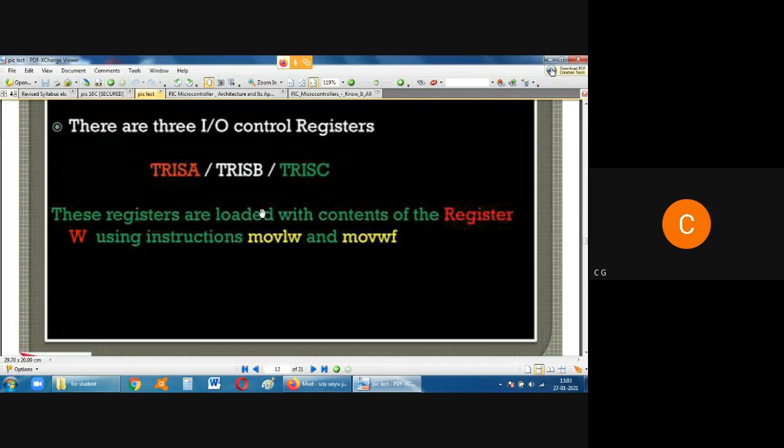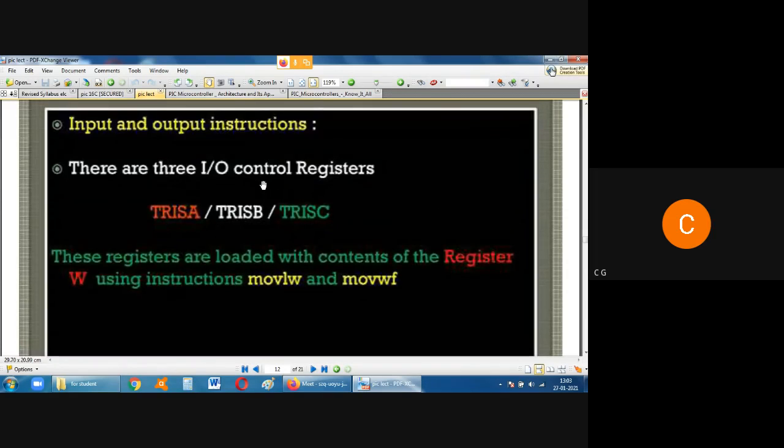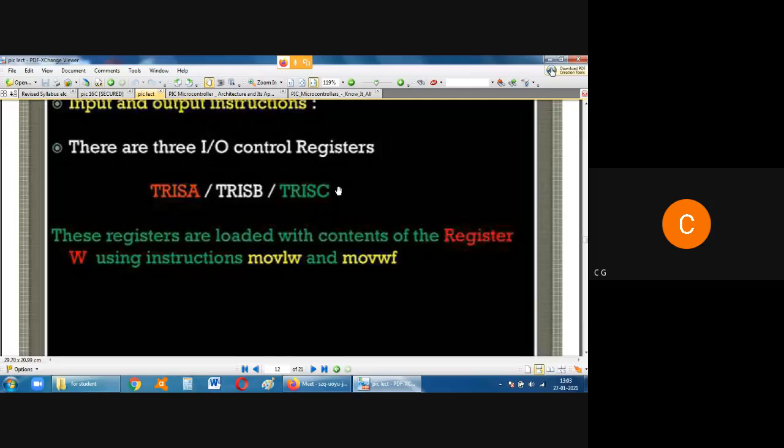This is kind of a hidden part because all these things are there. We write only the program. We don't know what is happening inside the microprocessor, microcontroller, and therefore we have to make sure of, even in the timing diagrams that we are not studying, how, when we give an individual instruction on the timing scale, it is decoded, then executed. Okay, so whenever any instruction is given or written in the program, the CPU will read the instruction from the memory location.